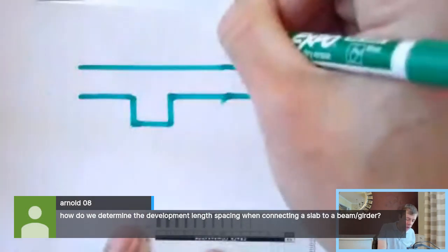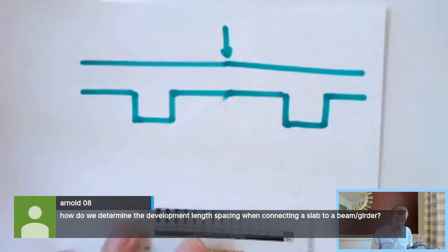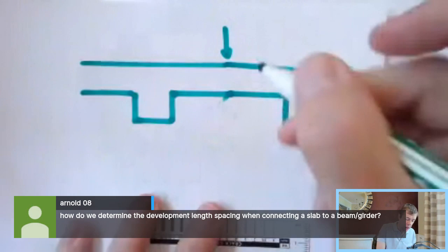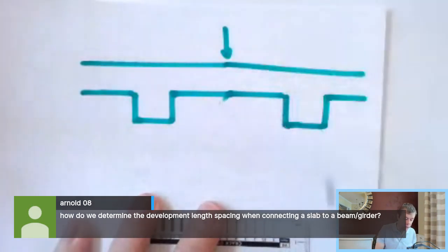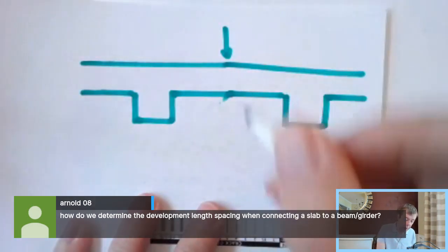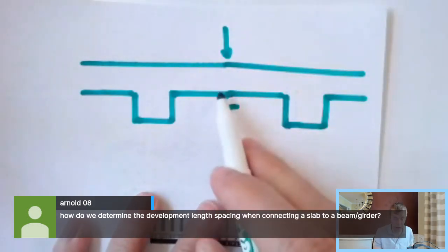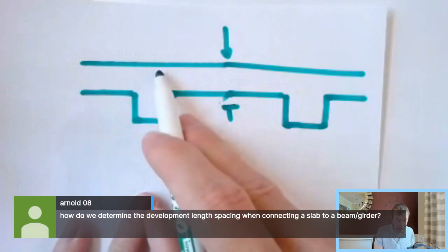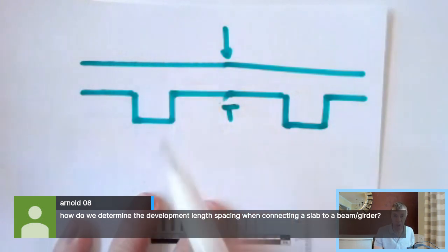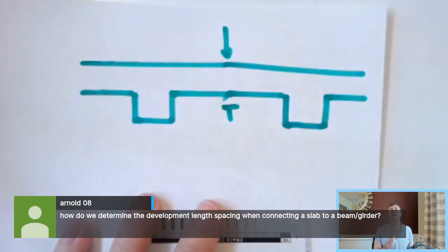And if I have some kind of load right here, so there is my slab, there's lots of different ways to think about this. I'm going to have tension down at the bottom. It's going to try to extend. That means I'm going to need a rebar down there. And you could think of having tension up here at the top, or you could just let it crack. You're like, what? What?